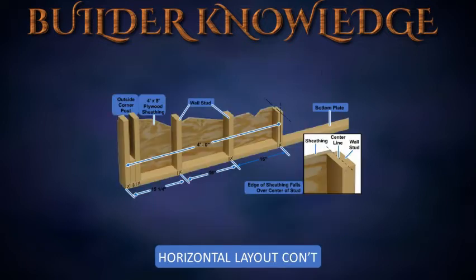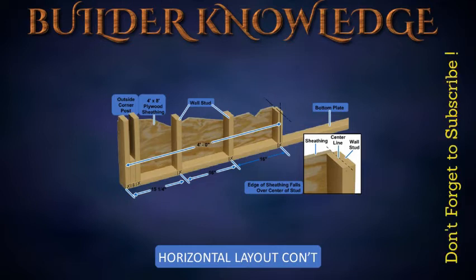For walls laid out to be 16 inches on center, mark the plates for the first stud from a corner post by measuring. This should be 15¼ inches from the end. Subsequent studs will follow the 16-inch on center layout. Lay out cripple studs to follow the stud layout.